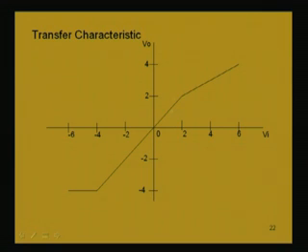So, this will be a straight line passing through the origin up to 2 volt. When it is greater than 2 volt, from this point to the peak point when Vi is 6, the voltage at the output is 4. So, these 2 points we can just connect. To get a straight line, a minimum of 2 points is needed. So, we connect these two.